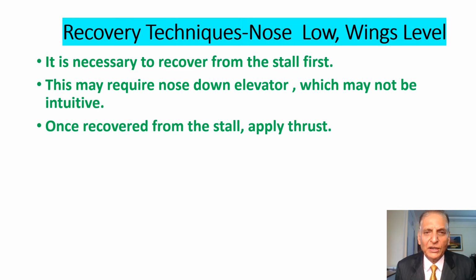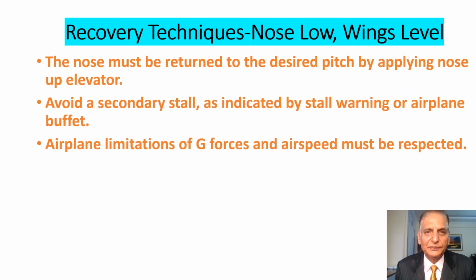Once recovered from the stall, then pilots can apply the thrust. The nose must be returned to the desired pitch by applying nose up elevator. Pilots must avoid a secondary stall as indicated by stall warning or airplane buffet. Airplane limitations of G-forces and airspeed must be respected.